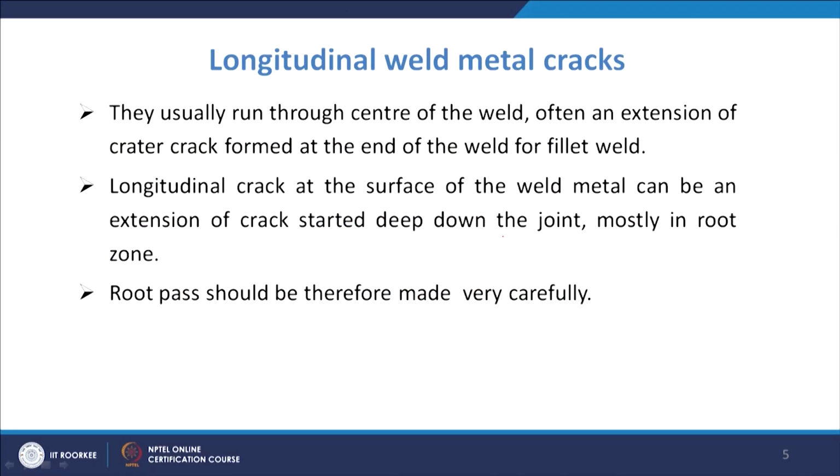So, for that not to happen, your root pass must be made very carefully to avoid the formation of these longitudinal cracks.